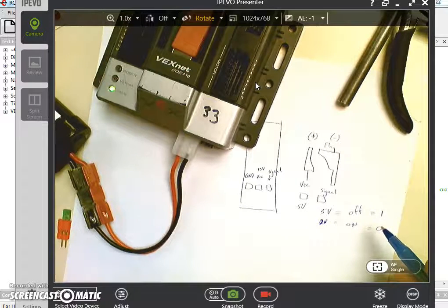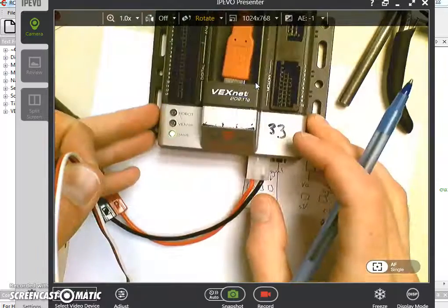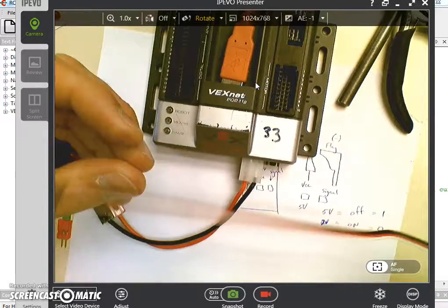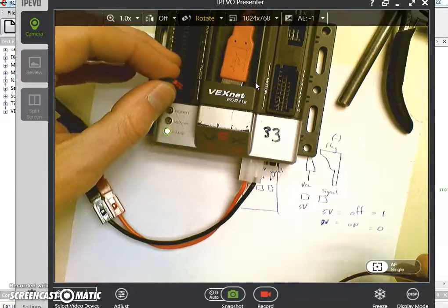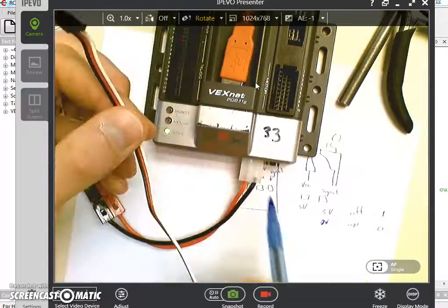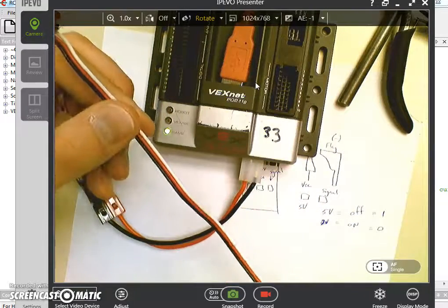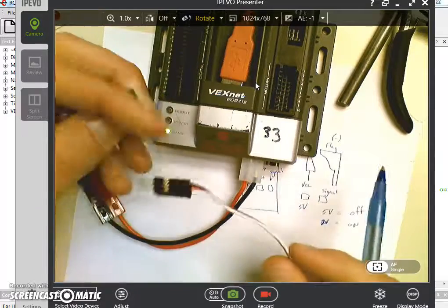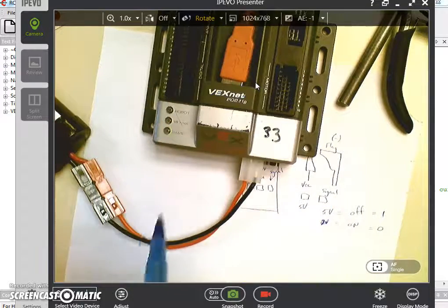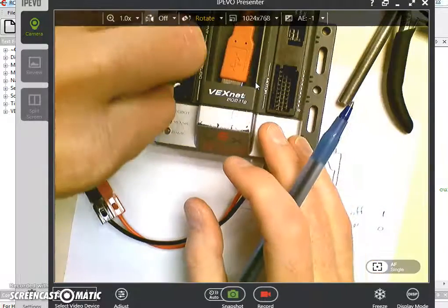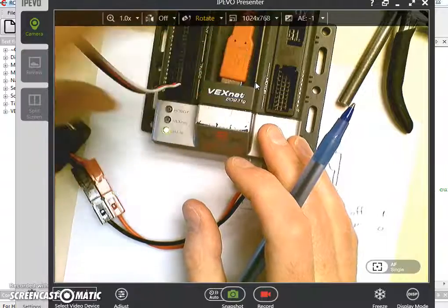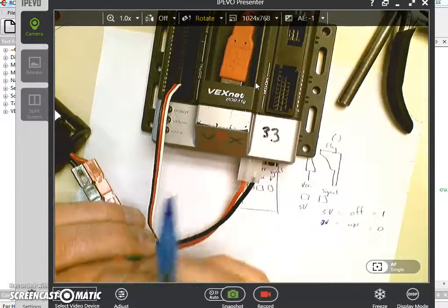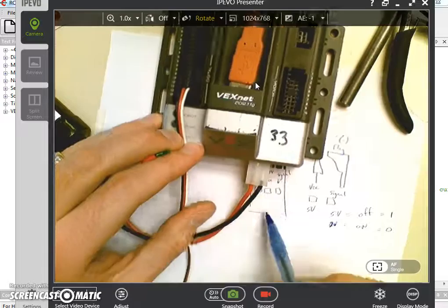So how do we hook it up to the Cortex using an extension? I don't want to plug this LED right in here anymore. I want to use maybe an extension wire to bring it somewhere else on my build. To do that, if you plug the extension wire in, maybe use port 11, you can see that my colors match up with what I've written down.